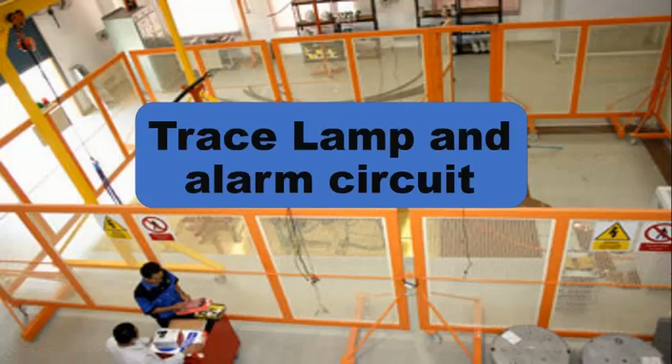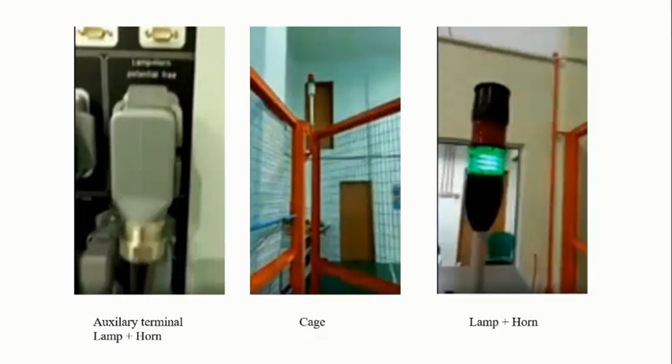Trace lamp and alarm circuit. First picture is the auxiliary terminal lamp and horn. Second is the cage, and thirdly is the lamp horn. The trace lamp and alarm circuit is used for safety. Every cage has the trace lamp and alarm circuit connected to the auxiliary terminal lamp and horn terminal for safety. When the red light is active, the injection or testing process cannot proceed, and when the green light is active, it is safe to proceed with the injection or testing process.